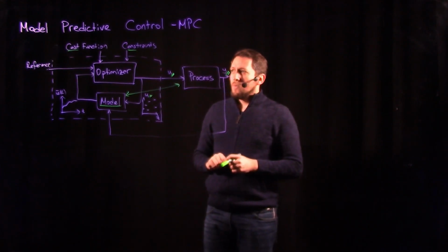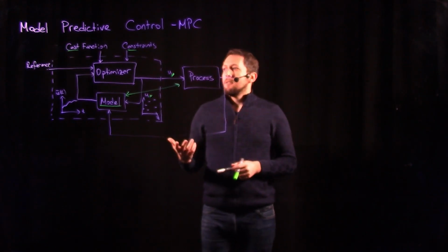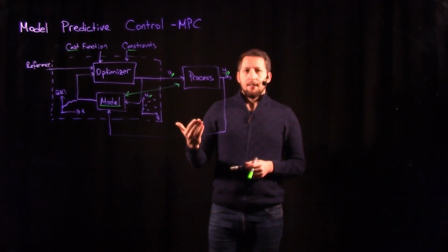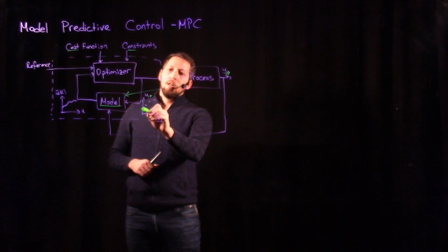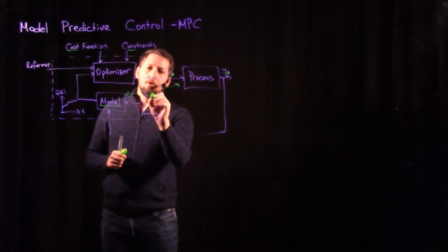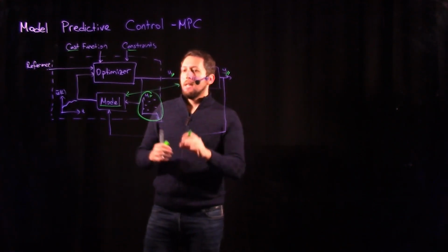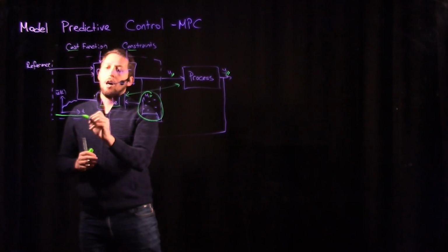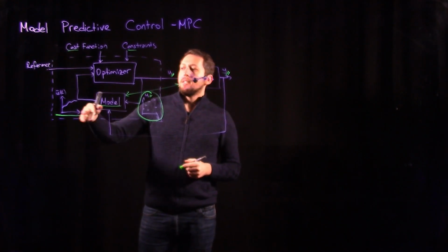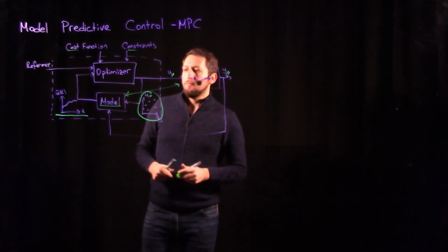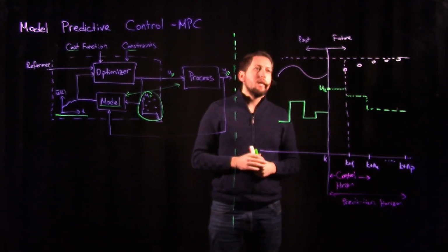Of course, some new terms arise here, like the control horizon and the prediction horizon. Here we are proposing a new control signal for a certain amount of time, and this creates a new output, the prediction horizon, let me say, showing how our system will behave in some certain future. So I would like to summarize the main working principle of model predictive control over this diagram.